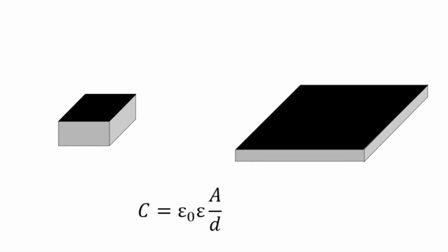The capacitance, though, is a function of both area A and thickness D. This means that the capacitance changes as the DEA is deformed. This capacitance can be measured, and when the capacitance changes, then you know that the elastomer is in its deformed state. Here we see the area in the unstretched rubber block, as well as its thickness.